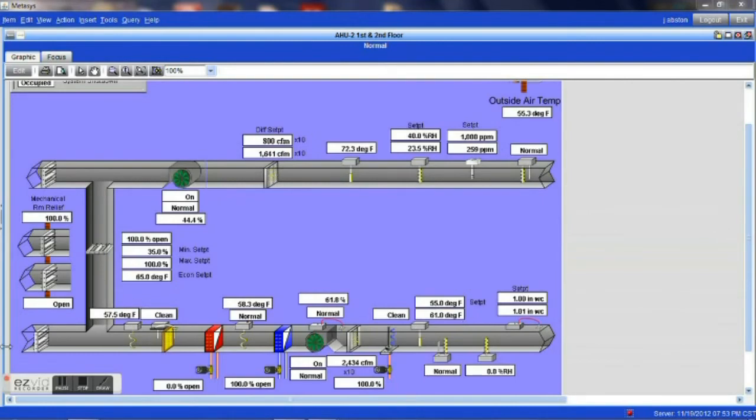It is more efficient in cooler days, cooler weather, to use outside air to cool your building. However, whenever the temperature is too high outside, when we are running our chillers, we will need a way of cooling the air, both the minimum amount of air from the outside as well as the return air from the building, down to the correct temperature for effective cooling. There can be times as well, if the air is too cold, that we will need to heat up the air using the hot water coil.